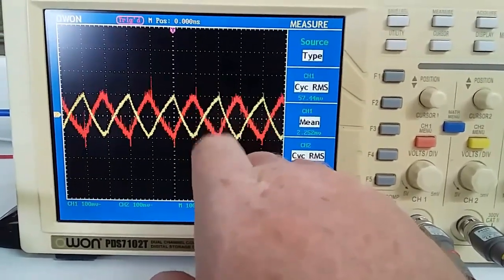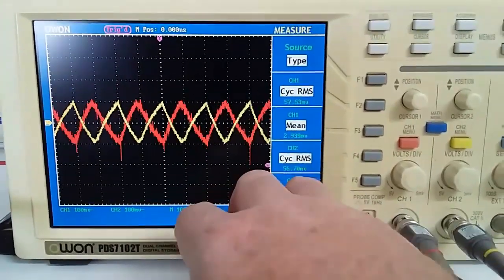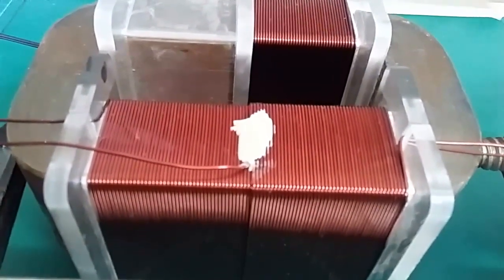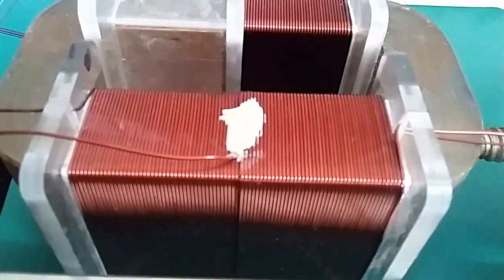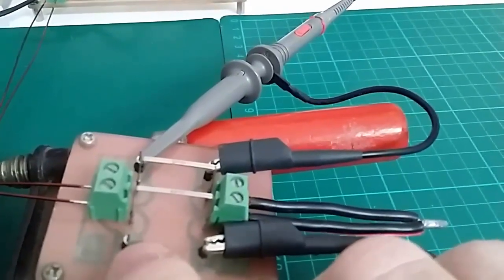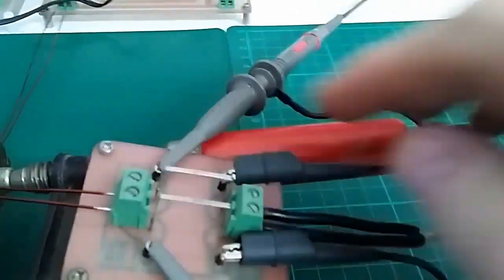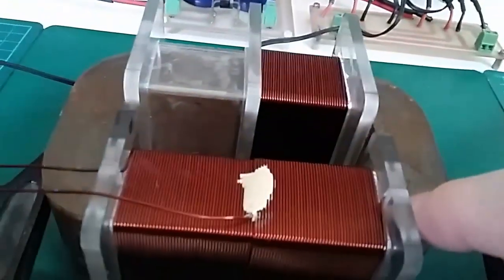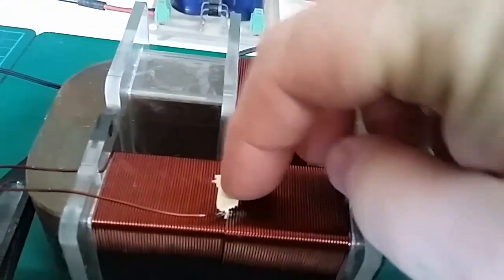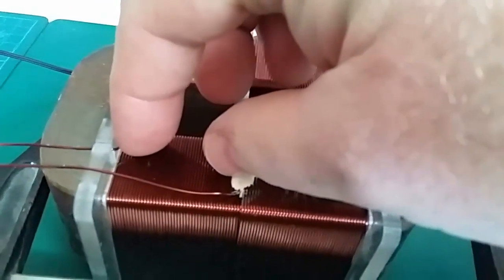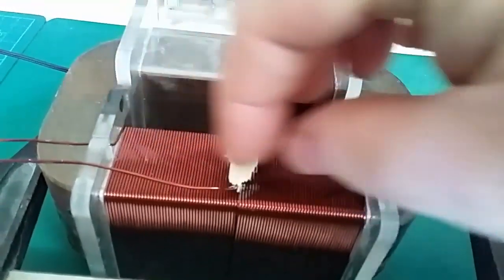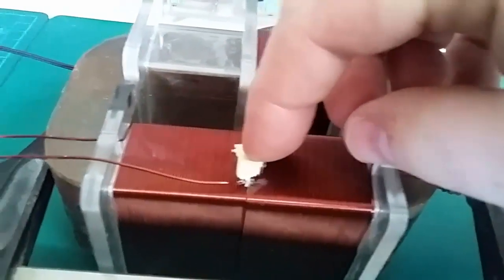Again, our coils are much closer to 180 degrees out of phase. Remembering that there is an inductance and a turn difference in our coils, the inductance and turn difference and also a resistance difference should give us a difference in current, but at this stage the current where we are tuned is the same. So this node here, this node over here, this node here is all the same. Remembering this part is non-inductive, this part over here is inductive. So from our input over here, this part is the only part that's being inductively coupled. This part over here is non-inductively coupled.